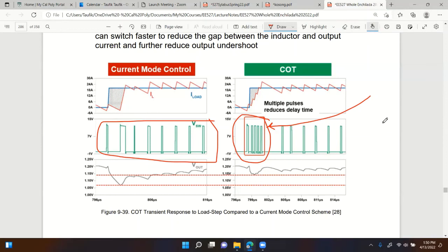So to me, that introduces some complication in terms of noise, for example, because now you have a noise spectrum that's all over the place, right? High frequencies and then the constant frequencies, right? Here, the noise is only practically at one frequency and multiples of that frequency. Here, the noise spectrum is much wider, right?